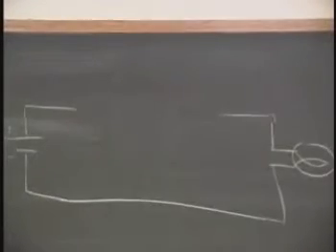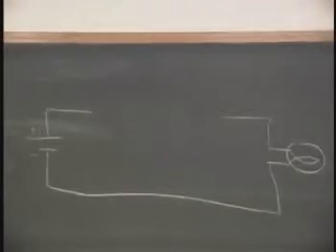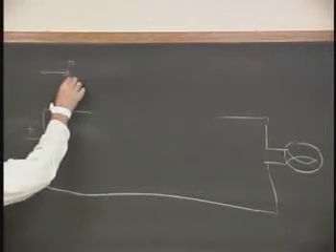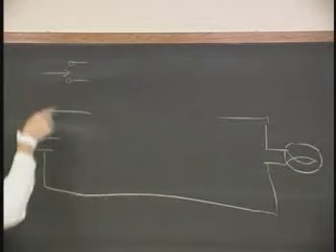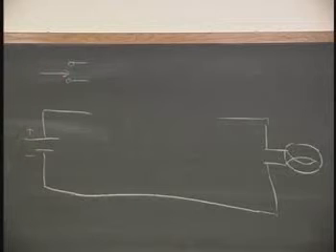So clearly if I hook this wire to here, the light goes on, right? How do I hook up two switches to act as XORs? There'll be some way to do it. I'll give you a hint. You can use a switch that has what's called two poles on it. So in other words, if I put it up, it goes to this path. I put it down, it goes to the other path.